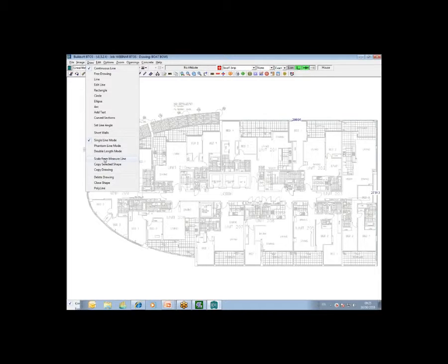And once you activate that function, the same pop-up will come up. Draw a horizontal and vertical line, draw a horizontal line, draw a vertical line, or diagonal line. So you can force the system, even with the CAD file, to accept the measurements that you have put in from 2 known lines. And that will, as such, overwrite the scale that was embedded in the CAD file itself.